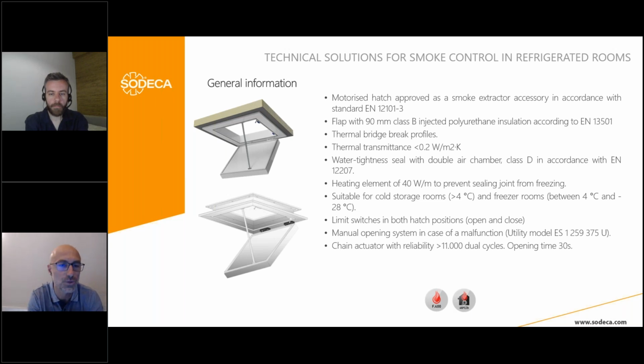It has 2 limit switches, both for open and close positions. It has a manual opening system in case of malfunction with this utility model. And it comes with a chain actuator with a reliability of more than 11,000 dual cycles. Dual means open and close. And the opening time is 30 seconds.